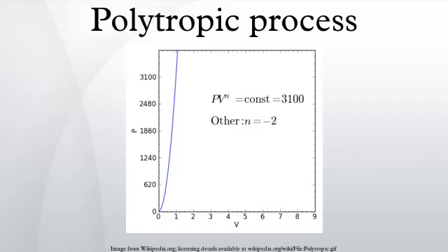This equation can accurately characterize a very wide range of thermodynamic processes, that range from n equals 0 to n equals infinity, which covers n equals 0, n equals 1, n equals gamma, n equals infinity processes and all values of n in between. Hence the equation is polytropic in the sense that it describes many lines or many processes. In addition to the behavior of gases, it can in some cases represent some liquids and solids.